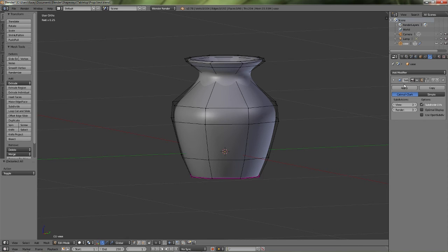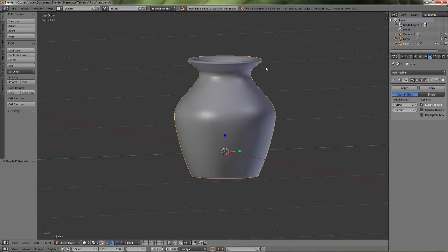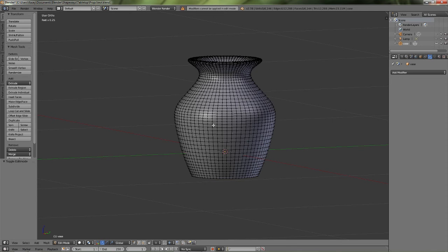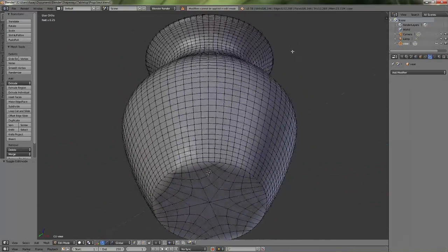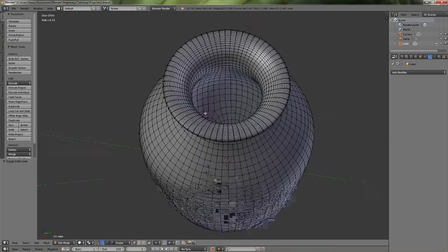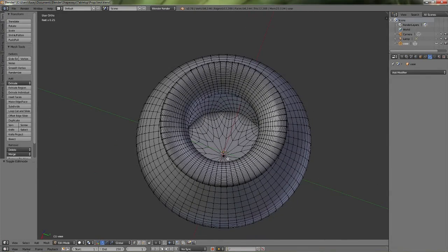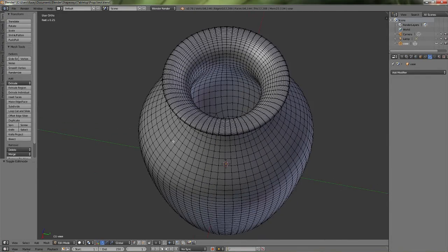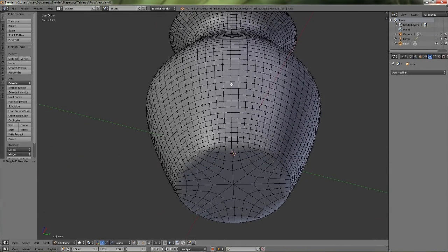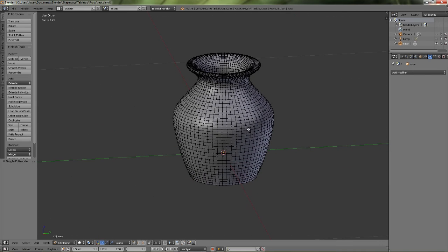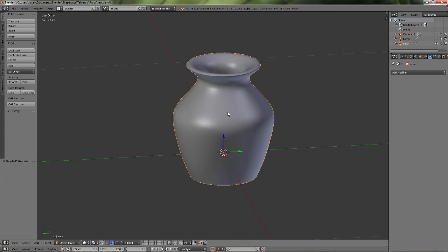There we go. Actually, let me show you real quick. If I hit apply and then go back, tab in, now the vertices are all exactly how they would be. But you didn't have to work with all of these because extruding that many times would have taken forever. So it does the hard work for you. So yeah, work smarter, not harder. Works nice. Perfect. So tab in and out, E to extrude, S for size.